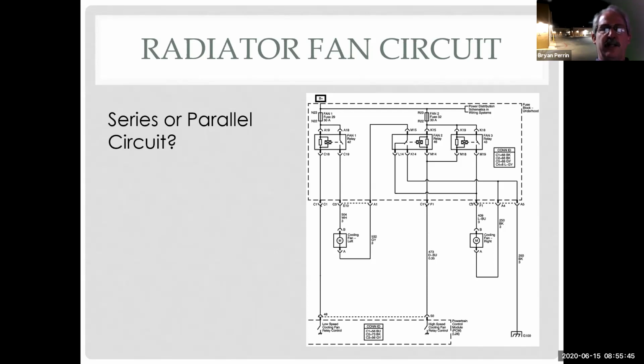So that way it's not dependent on the thermostat to open, and it measures the engine temperature and turns the fans on based on the engine temperature. And that's how most modern automobiles work. We haven't used fan switches in the radiators really since the 90s.